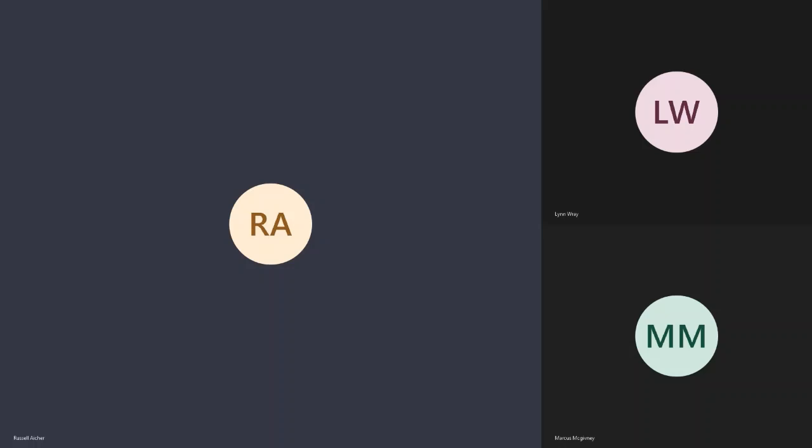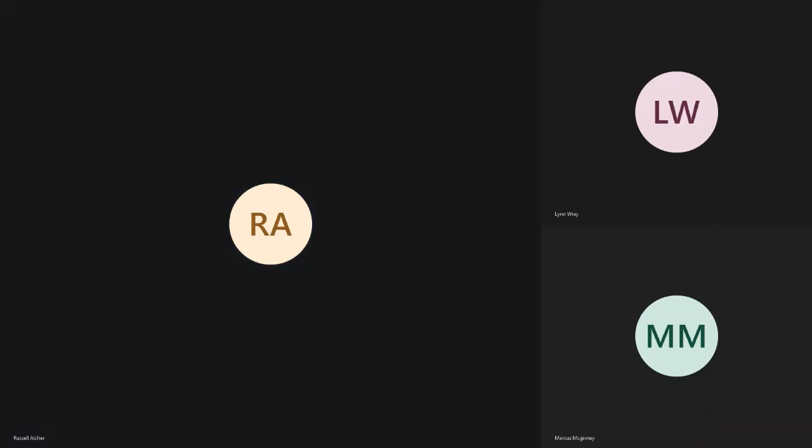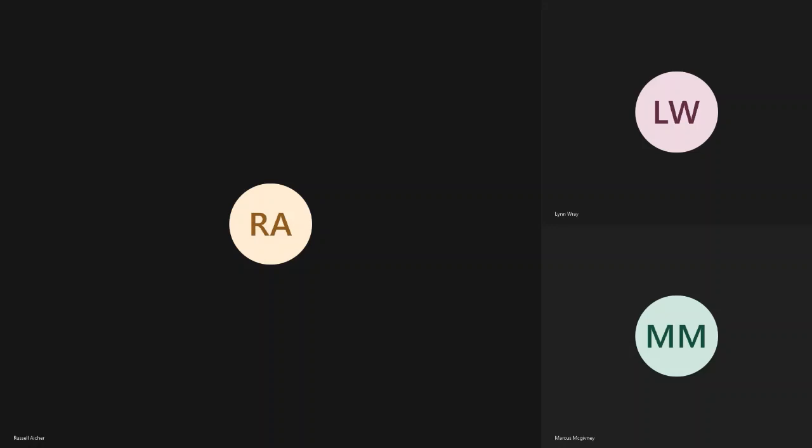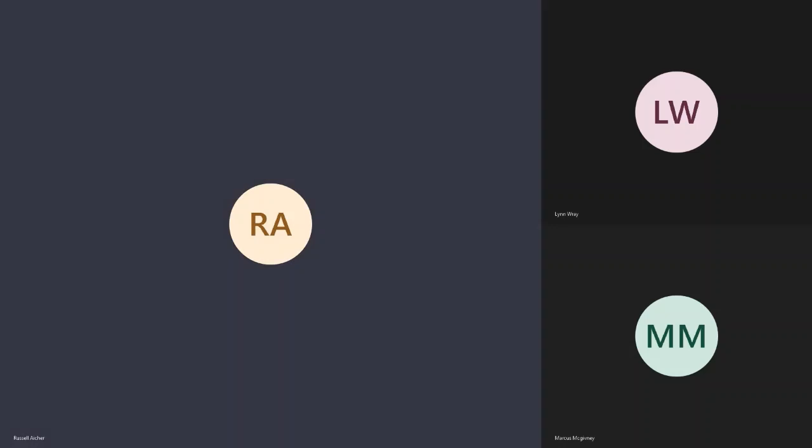Okay, if you want to do cool stuff with vector data and topology, you have to use a geodatabase. You can't use shapefiles, and ARC doesn't like coverages anymore, which is too bad, but it's the way it is. So you have to use a geodatabase. You have to use either a personal geodatabase or a file geodatabase, but the personal geodatabase is going to go away when we go to ARC Pro.